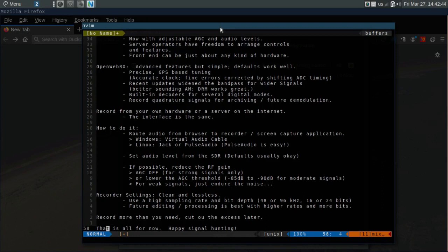And it's very good because it's very customizable. You can set the audio gain, the RF gain, the filters, and it also has built-in digital decoders. It has an IQ mode where you can get quadrature output, and you can feed that into a DRM receiver or some other kind of digital demodulator on your own equipment, and you can do some sophisticated DSP work with that.